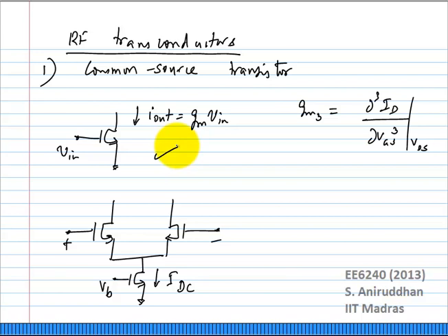The reason we started off with the sidetrack on the mixers is to decide whether VDS is constant or not. What you know is that VDS is going to be more or less constant. So you can figure out for that VDS what the GM3 would be, and you can characterize the third order nonlinearity of this. Of course, we have seen before that you can bias it such that it has very low third order nonlinearity. Apart from that, can you do anything else to help?